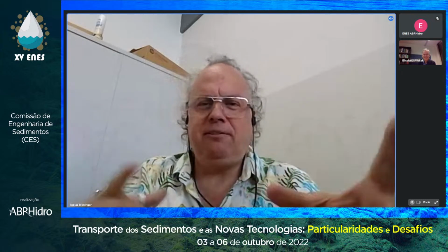And this brings me to my question, actually. It's about how you measure reservoir sedimentation. So we did quite some studies here at one specific reservoir using bathymetrical surveys, but also using sub-bottom profilers. And this provided us volumes, but not mass. We recognize that the reservoir bed is like a pudding, so it's very fluidized beds. So the volume does not necessarily inform about mass.